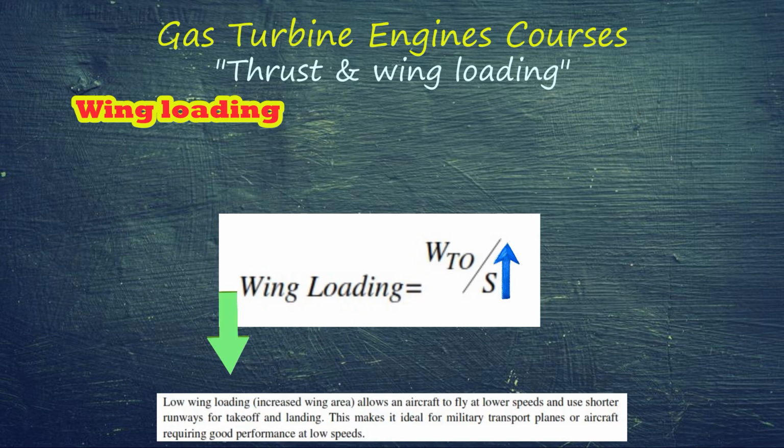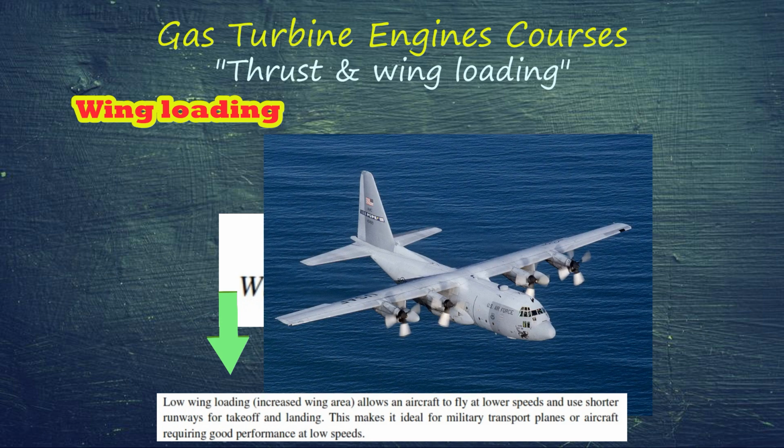Low wing loading allows an aircraft to fly at lower speeds and use shorter runways for takeoff and landing. This makes it ideal for military transport planes or aircraft requiring good performance at low speeds.